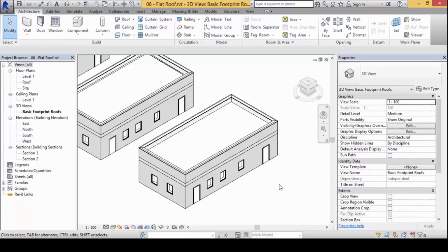Water is pretty heavy. Water has weight, by the way. Small like that, okay, I can manage. But when you have a huge swimming pool, it's a couple of tons weighing onto the roof, which is not designed thick enough, or not designed to become a swimming pool. So what happens is water builds up. First things first, because of the structural deflection drops, waterproofing fails, opens up cavities, and water drips.